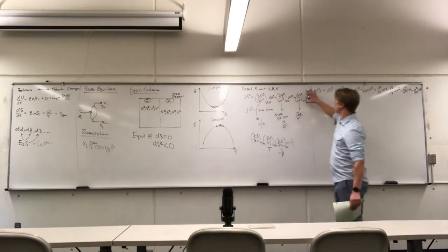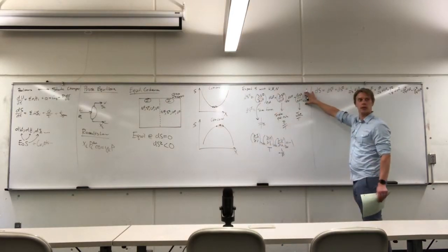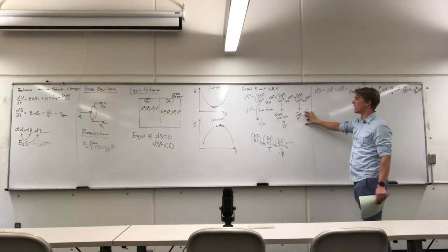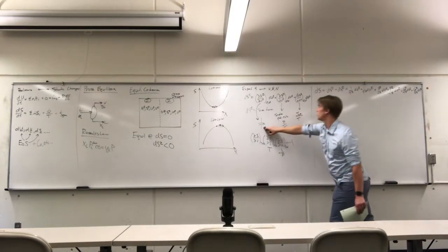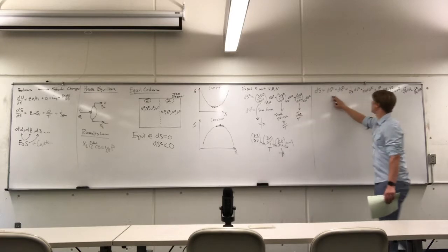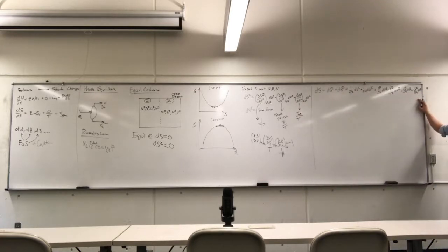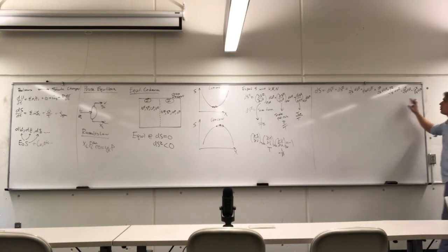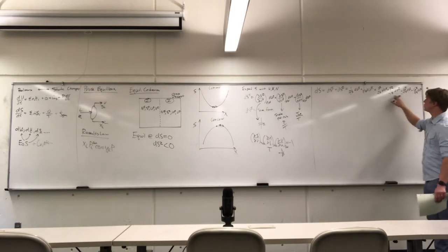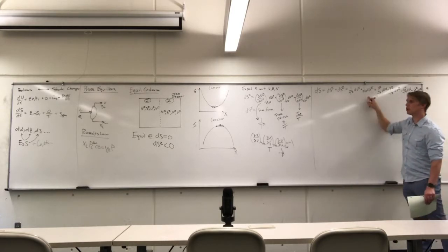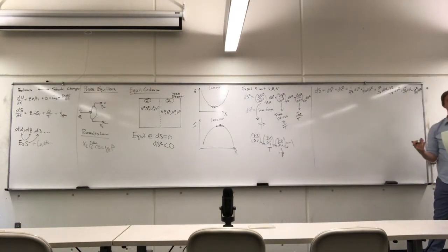And so we've accomplished that for one chamber here, where we've combined this with our first and second law to give us useful expressions and more or less definitions of temperature and pressure. And then we're just keeping track of all of the different ways that entropy can change in the system: by mass going to chamber 1, mass going to chamber 2, the volume changing between chambers 1 and 2, and the internal energy being exchanged between chambers 1 and 2. We're going to come to them as phases.